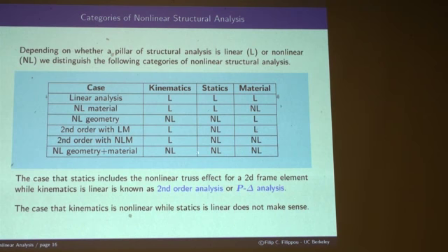Okay. The nonlinear geometry case means that both the kinematics and the statics are nonlinear, exactly as I showed you. You would obtain this in OpenSees using the transformation class Corotational. That's the only transformation we have for this nonlinear large displacement, right? Okay. So you will include that if the material is linear, which is possible.